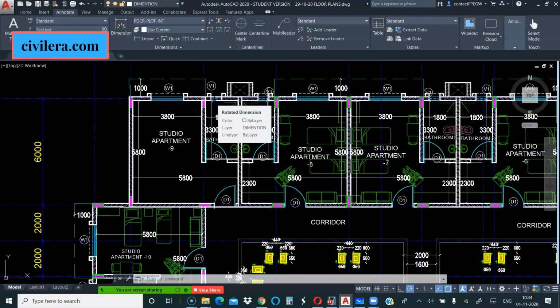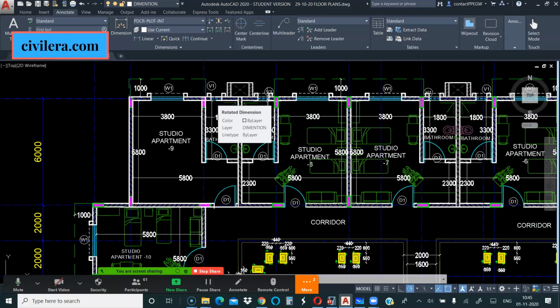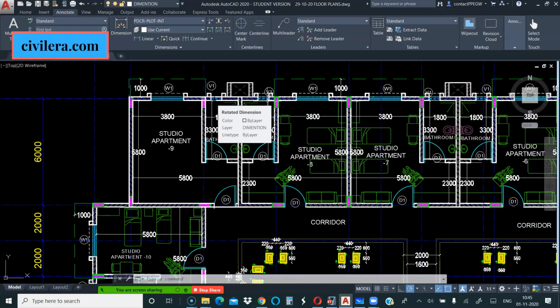Some architects will indicate some columns based on their experience, so that we get a base, we get an understanding of where he is okay with the column, and sometimes they won't place any column. You have to place all the columns. In any case, it's our responsibility or our decision to decide the location of the columns, keeping in mind structural location, structural importance, structural requirement, and architectural aesthetic part and functional part and things like that.